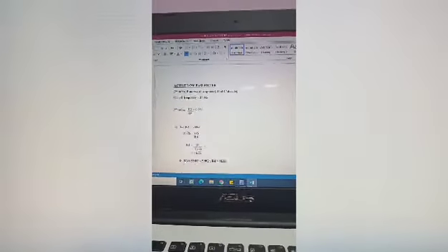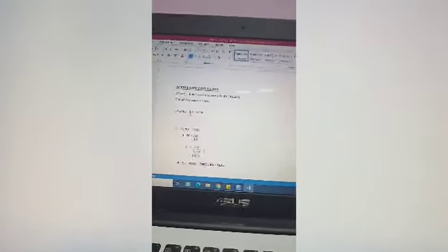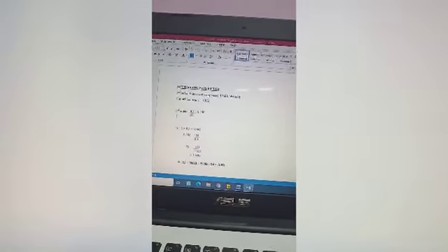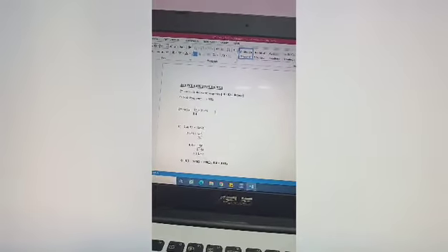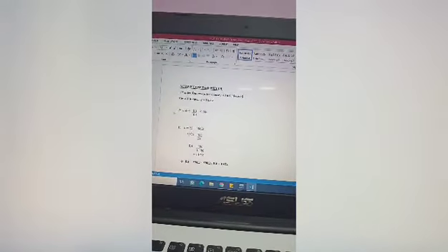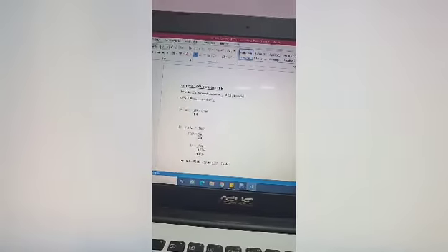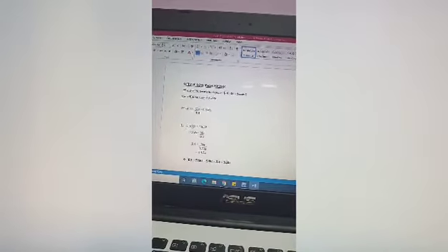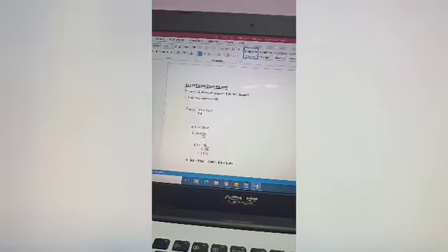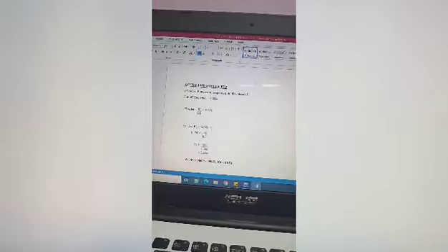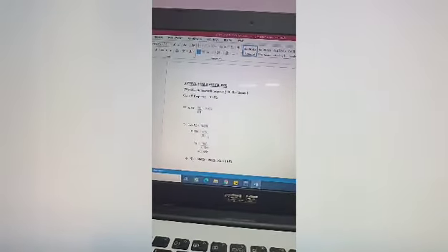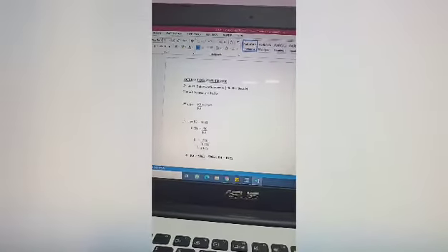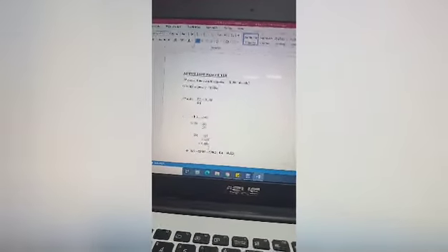The given cutoff frequency is 8 kHz. From the Butterworth response, we know that for the second order, R3 over R4 equals 0.586. We need to identify the value of R4. So we assume the value of R3 as 586 ohm. Using the value of 586 ohm, we identify the value of R4. Thus, the value of R4 is 1 kilo ohm.